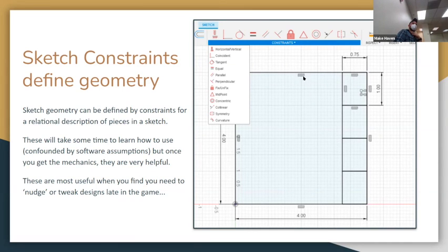The other thing that's worth knowing in Fusion 360 is that it uses these little grayed out logos to show you that all of these lines are supposed to be vertical or horizontal. And then this tells you that these boxes are all in an array, that they're all from like a combo pair. So these are the little hidden symbols in Fusion 360 that seem like details, but they're definitely important details. It's part of Fusion 360's 360 things to learn at once, which is actually fine. And the more you get into it, the more you like it. But it can be really helpful if you want to define certain things with your shapes.